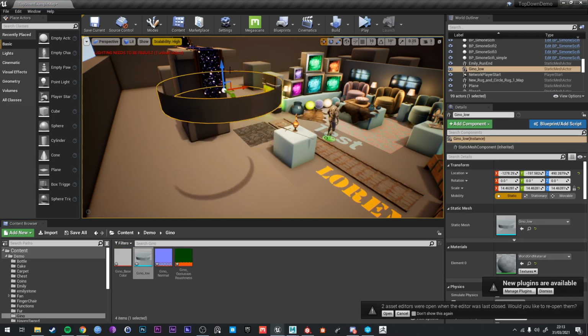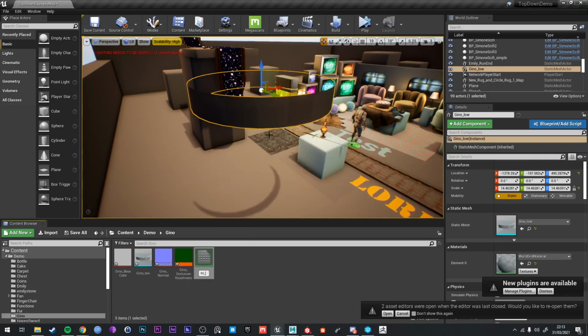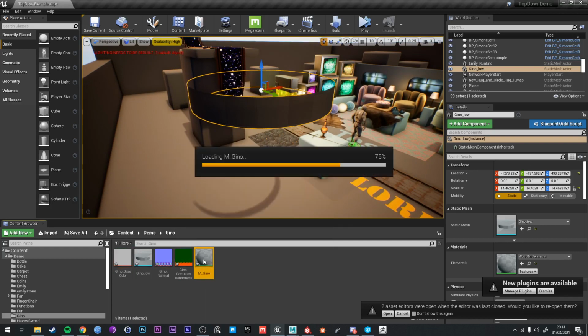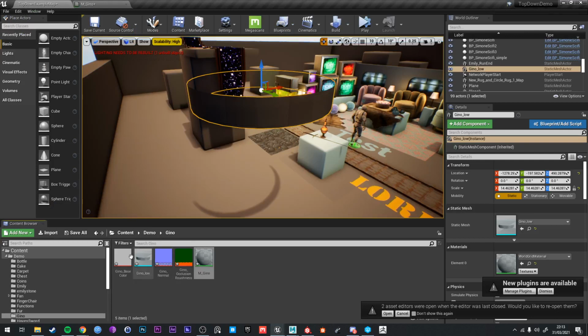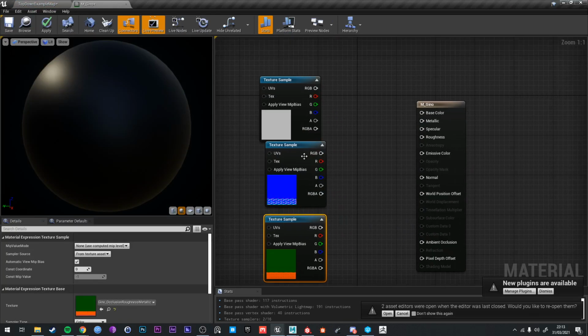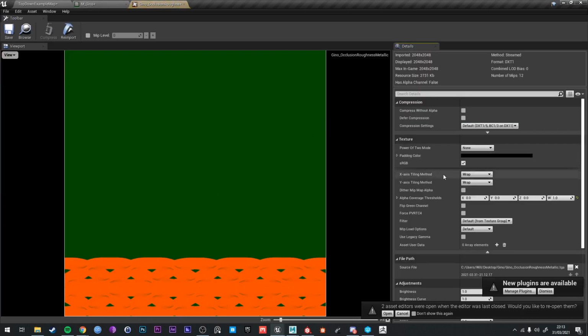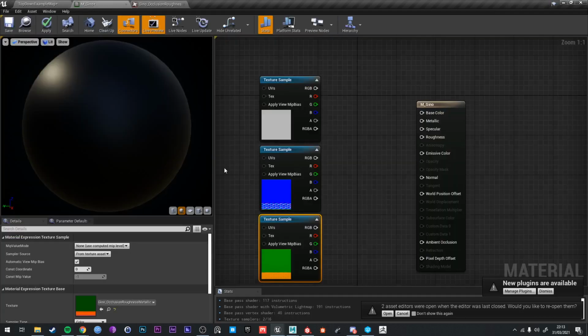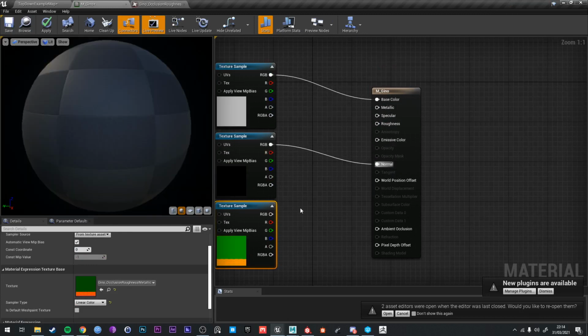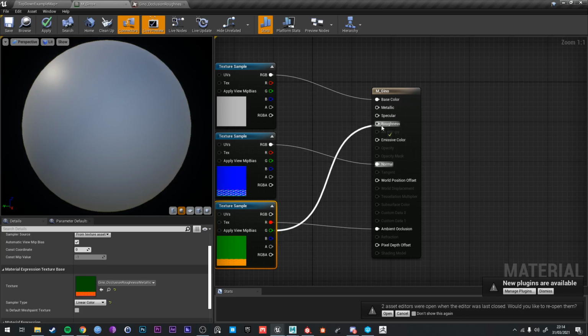Let's make it really big so we can see. And let's make a material. Geno, so this is all stuff we're going to cover in week 3, which will actually be week 5 for you guys, because you have Easter break. But I want to just show you the whole workflow here so you understand what we're doing. With mask textures, we're going to be learning about sRGB and why we need to turn it off on our opaque textures as well, but once again, don't worry. Base color and base color, normal and normal, ambient occlusion, roughness, metallic.